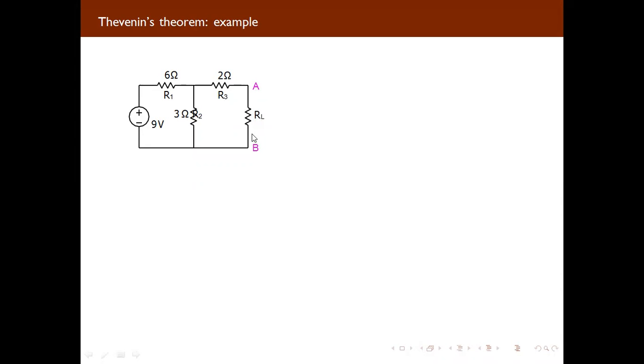You can consider this as an open circuit, because in the Thevenin circuit we are converting a complicated circuit into a simplified one, where we get the Thevenin equivalent voltage source and the Thevenin equivalent resistance. If there is RL, we can connect it as it is at the output.